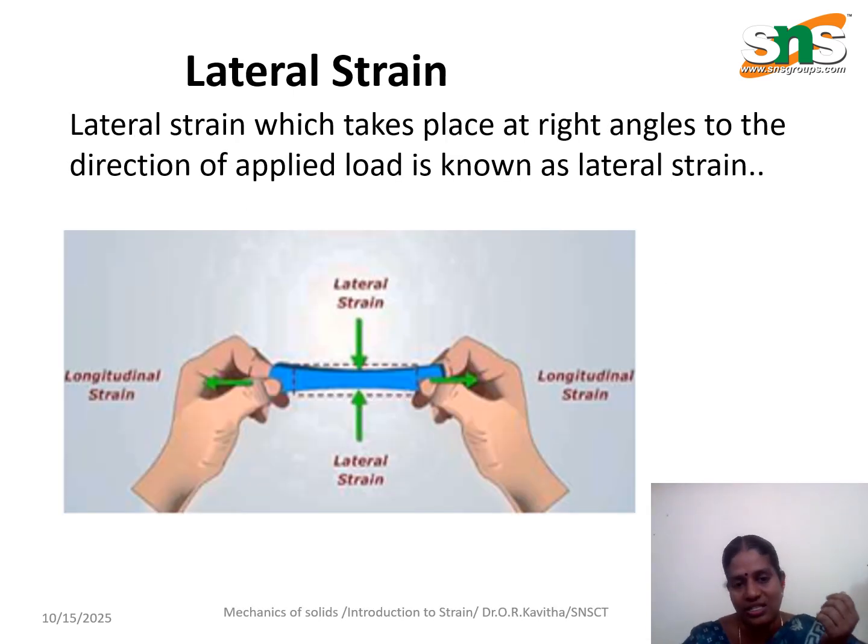And next one is the lateral strain. Whenever you apply a tensile load, the longitudinal dimension will be increased, but automatically the lateral dimension is reduced. That is nothing but the lateral strain. The longitudinal strain and lateral strain will always be perpendicular to each other.